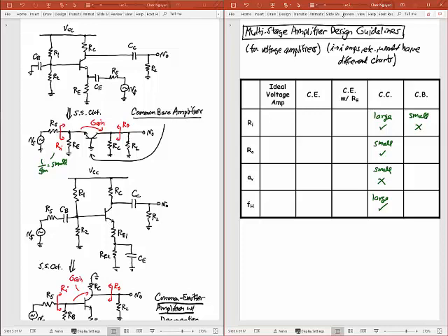Continuing on, I can look at my output resistance. What's the output resistance of this thing? Just by inspection, I will see, yes, an R naught there. I'll actually see even more than that. It's going to be R naught times the rest of that stuff that comes with R naught, but that's going to be in parallel basically with this RC here.